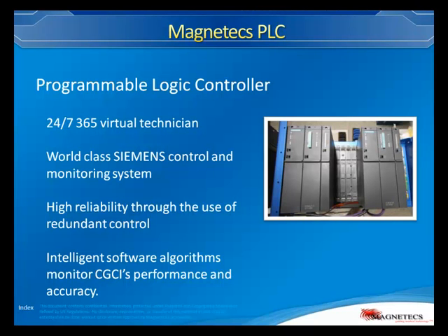For example, a catheter will not move in the heart more than 20 millimeters per 3 seconds. There's no use for the physician to rush in the catheter. Therefore, if the physician actually ran the catheter to increase the maximum forces on the system, the system will reduce the amount of forces required, because the heuristic manager says you cannot translate more than 20 millimeters per 3 seconds, no matter what. So no matter what the command, it's overruled.